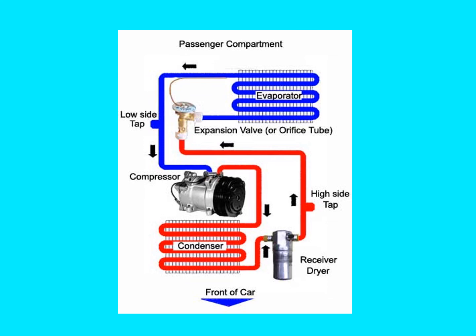It's going to start to vaporize into a vapor, low temperature, and it's going to completely vaporize inside the evaporator core and move as a vapor to the compressor as a low temperature vapor. And that'd be the refrigeration circuit for a TXV system.